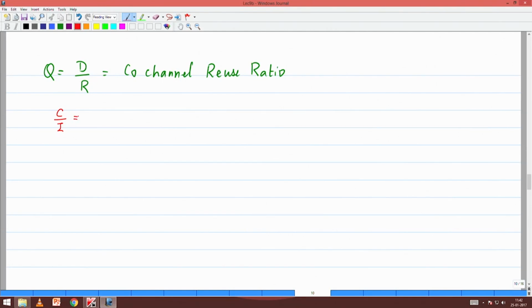So now I want you to visualize this signal power. I have only one source of desired signal, that is PS. Now the interference can come from multiple interferers. So let me call the index i equal to 1 through some I naught, some number of interferers. Why is my interference number not fixed?